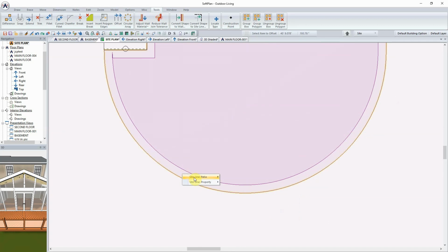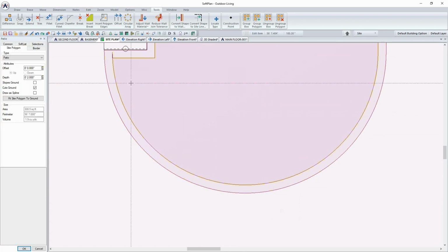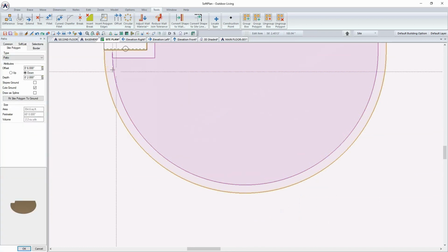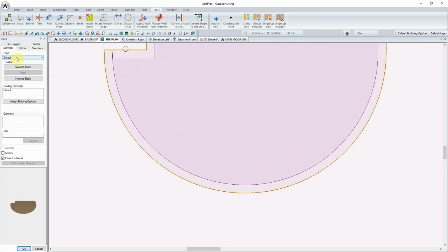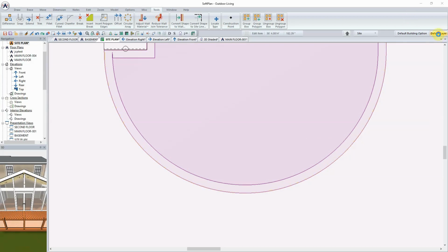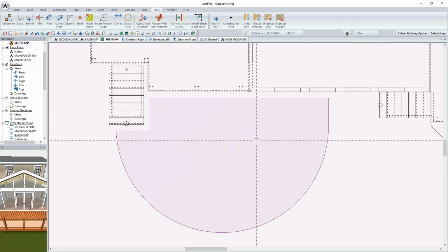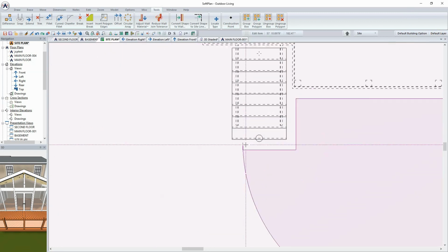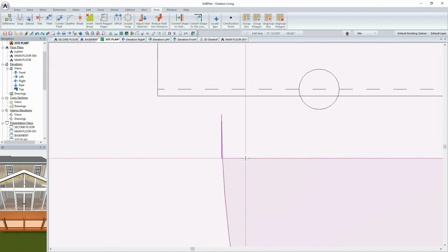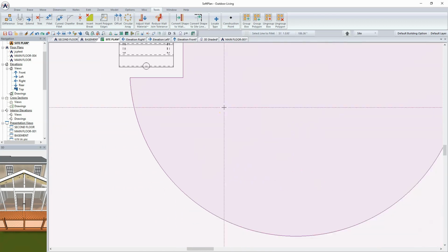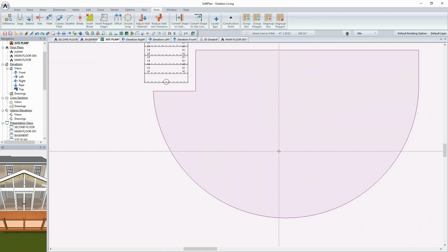For the time being, as that's the one that I wish to work with, I'm going to edit the outer polygon shape that is here, and I'm going to set its default layer to 1, and then turn that layer off. And so when I do that, I now only have the inner shape to work with. Here, I can now come in and I'm going to fillet these two edges, something like so, just to clean that corner up right there based on when I offset things in.